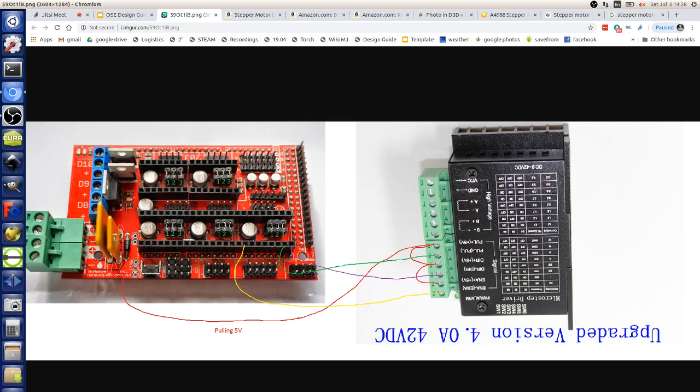Yeah, the higher speeds at higher voltage refer to one of the properties of the stepper motor, which is its inductance. There's both resistance and inductance in a stepper motor. The higher voltage you can push through, the lower the inductive effects. In other words, you can get it up to speed faster, and therefore you're able to achieve higher speeds, because at a certain point you get back EMF from the coils, and that back EMF effectively reduces the voltage you're applying to it. So if you have higher voltage to push, you can effectively drive a stepper motor faster.